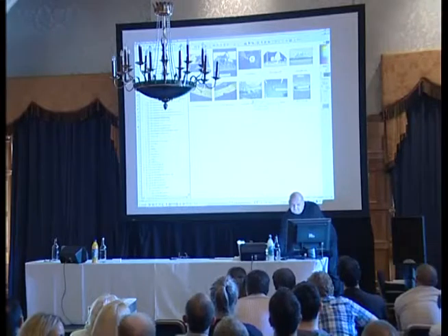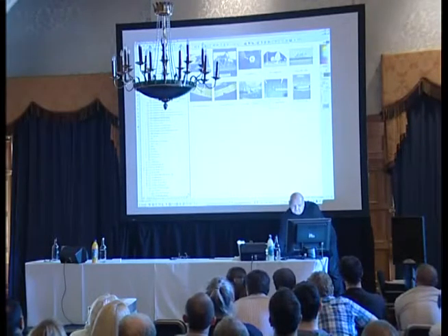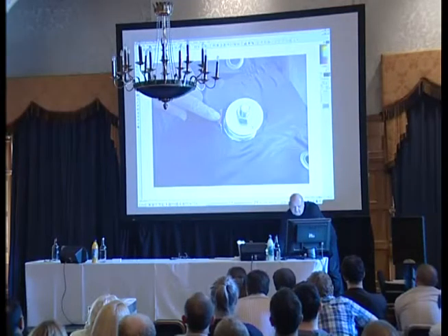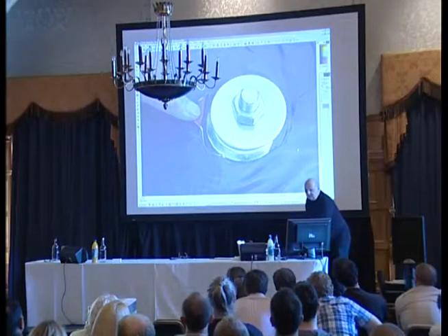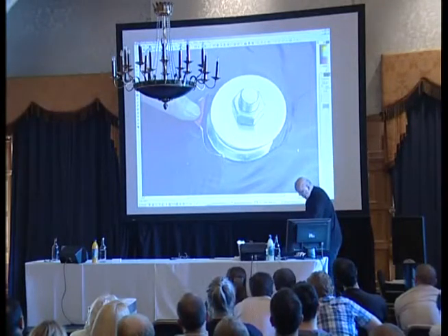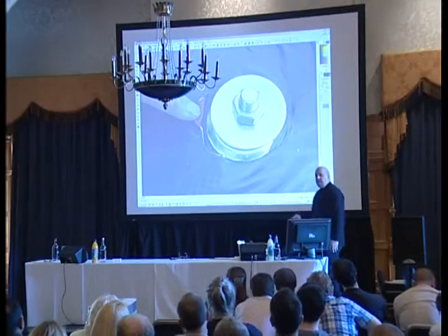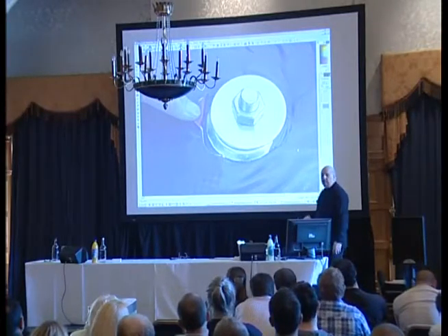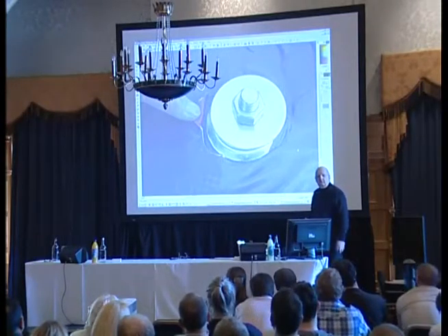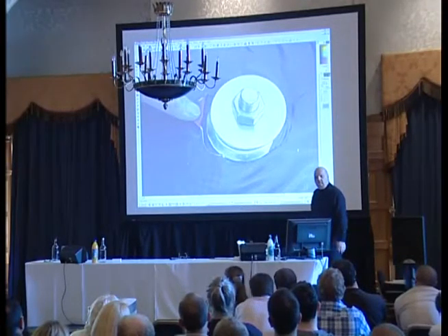Damn, I even got that piece on there. I don't know if you can see that. Can you see that there? Running underneath that seam, there's a seam running down here. It's a 5-ton, 50mm wide plastic webbing. And they've punched a 40mm hole through it to put that clamp on. So the webbing's got 5mm either side. And of course it's sheared.